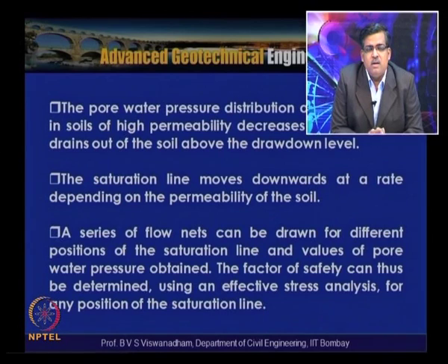So as the slope comes close to the equilibrium condition, or just after the rapid drawdown, we can determine it, and once the slope reaches some equilibrium condition, we can determine it. The vulnerability is that immediately after the drawdown condition the factor of safety reduces, so for that condition we need to ensure that it has an adequate factor of safety.